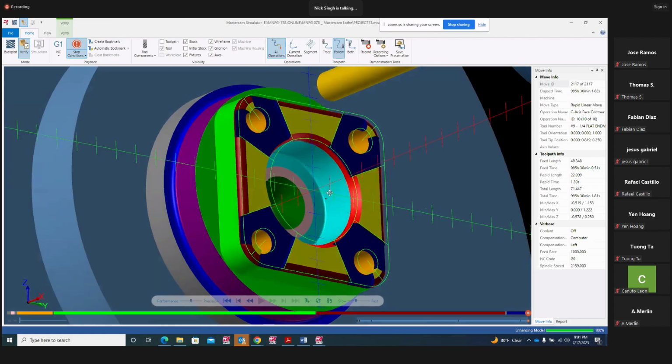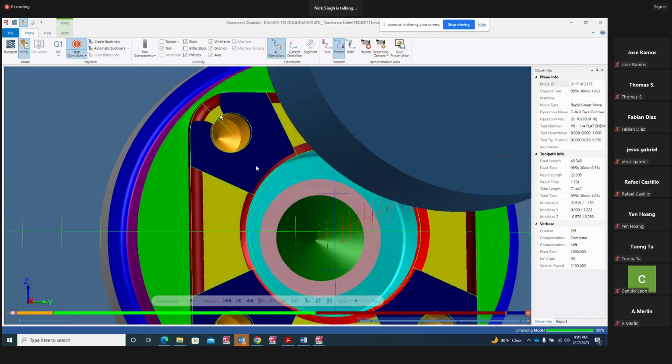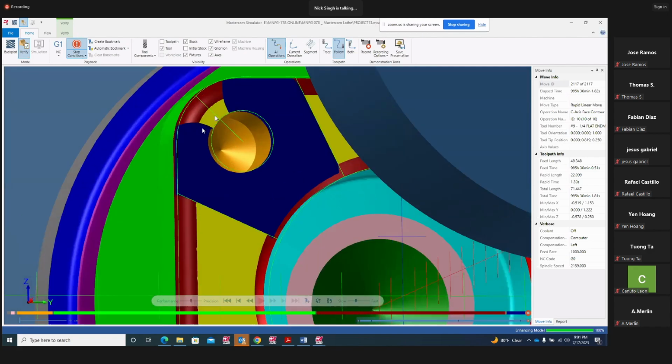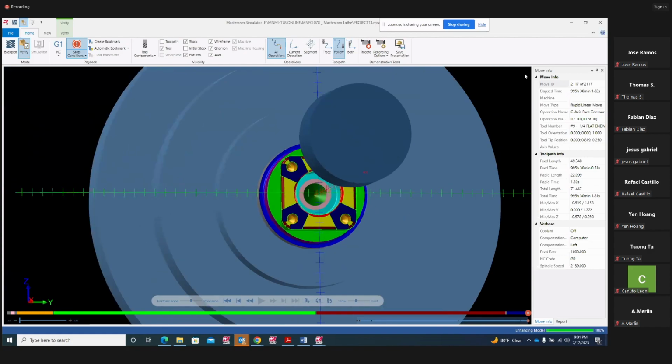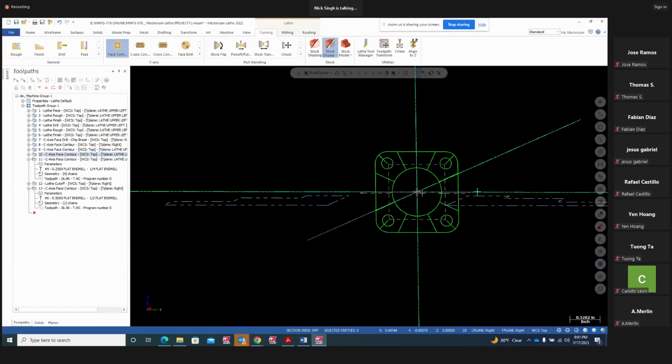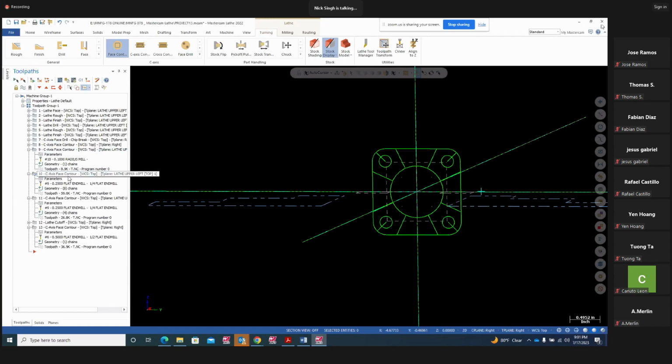There you go. So now the last tool path is going to take care of whatever is left over here, this material. So we're going to use a quarter-inch end mill, use these lines right here, the ones we have drawn. These lines, we're going to use this. So going back to tool path number 10, for your face contour, quarter-inch end mill.